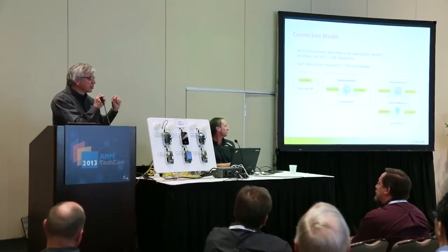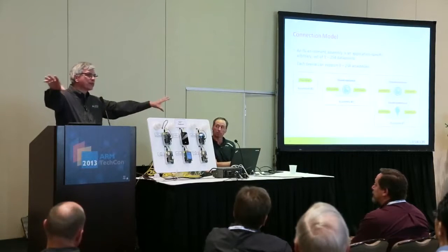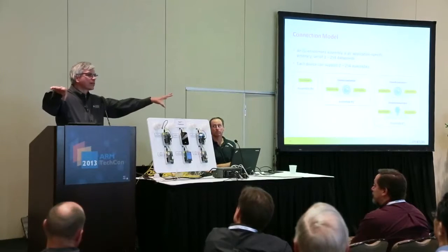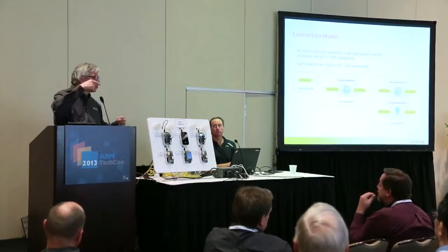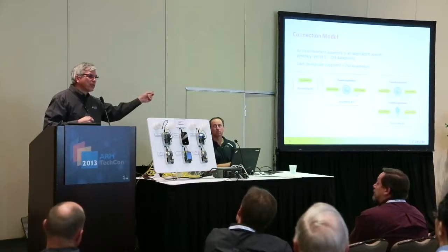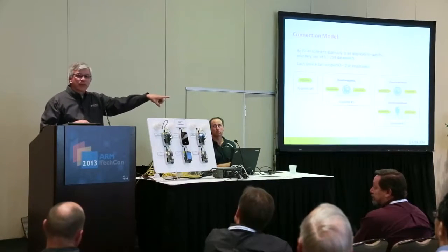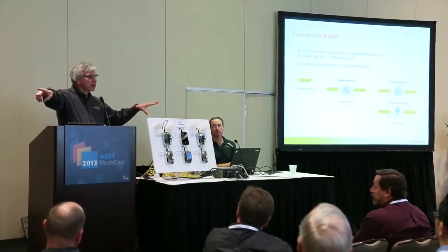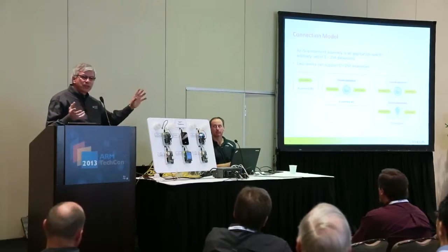So each one is sensing local occupancy, saying, oh, I see occupancy there. But envision that they were in 2 ends of the room. And so at one end of the room, the sensor sees that the room is occupied at that end. The other one doesn't see that. But the two sensors could be tied together. So the outputs of the two go to the inputs of the two. So the other sensor would not only be able to sense physical presence, that there's somebody over there, but get data from this device saying, oh, there's actually someone in the room just at the other end where I can't see it. So that's a closed loop sensor where you have inputs and outputs.